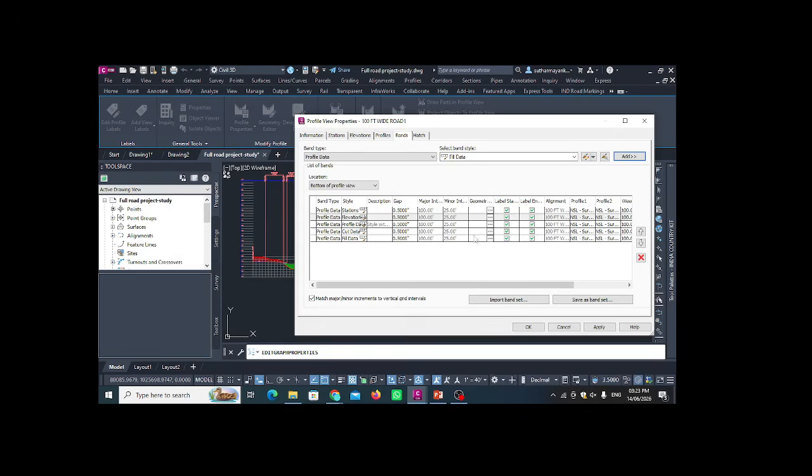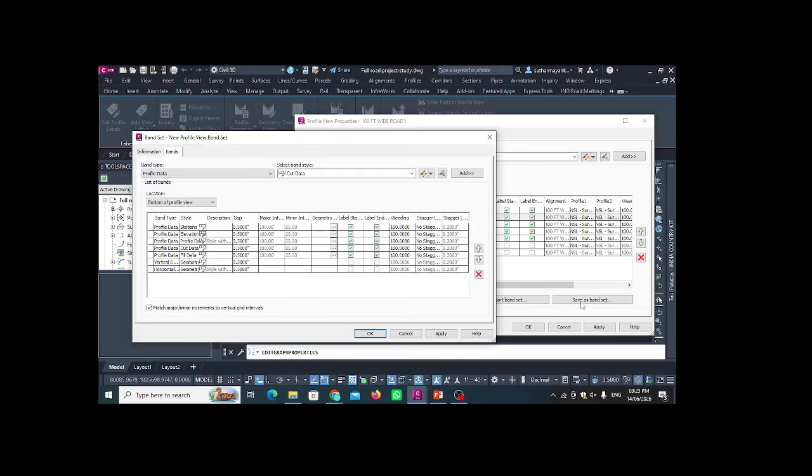Now, if I want to provide a vertical geometry, then I select the vertical geometry from here, and I add the geometry data here. Then I provide the horizontal geometry, and again I add the geometry part here.